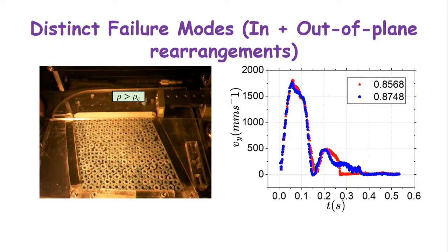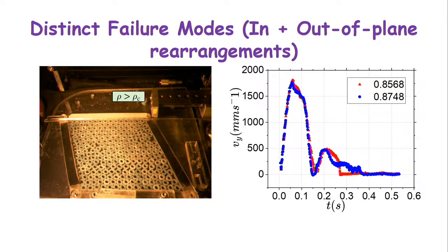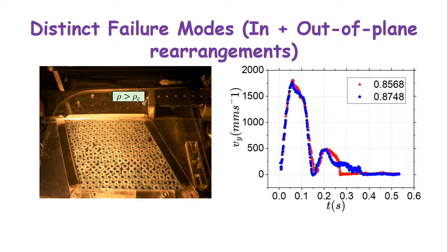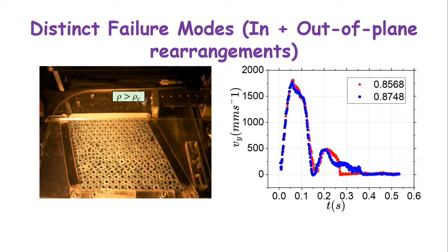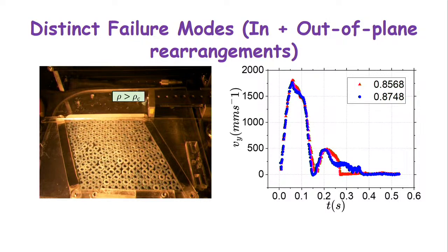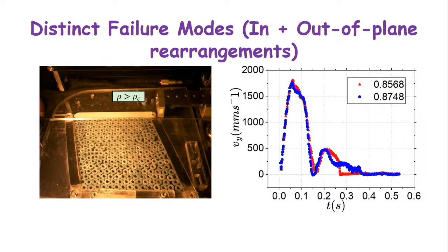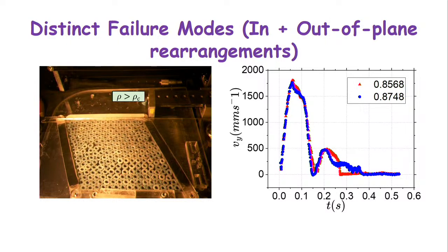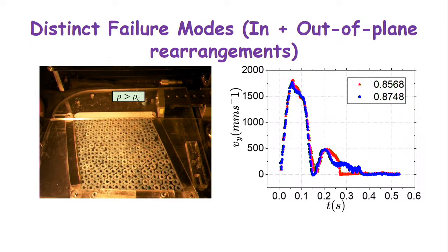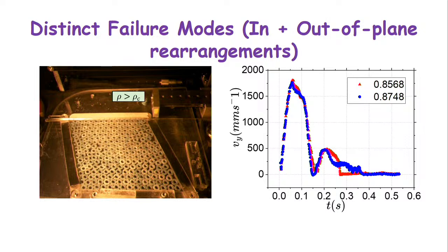You can see it for the other case too: it almost comes to a halt, it breaks, and then goes up. So whenever the density is greater than the critical density, the speed slowly goes up for a longer distance. If you just look at the plunger speed, it's very different when you are below the critical density or above the critical density. It's much more drawn out up here.